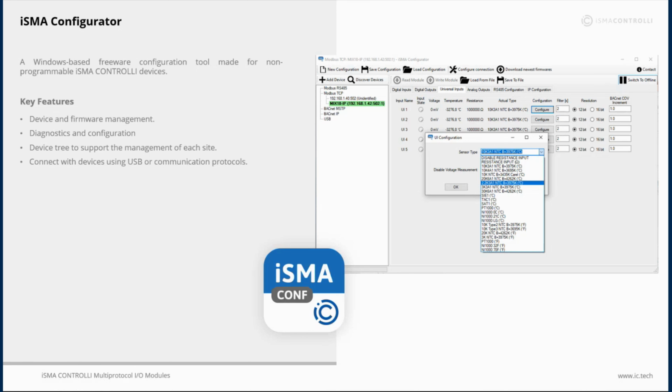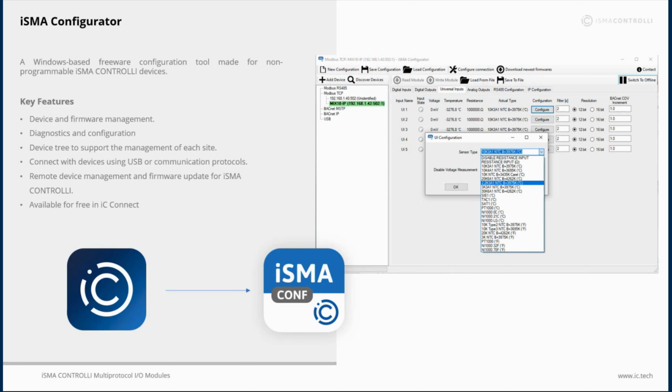You can connect to these devices, as I mentioned, to all devices using the mini USB cable, but you also have all those communication protocols implemented, and you can even do the discovery process over Modbus and BACnet. And what is important, even for devices connected over RS-485, you can remotely manage. We have a special module for Niagara for Modbus, and our products support products including MAC36 and JACE, which support BACnet routing. So you have a remote access not only to the IP devices, but also to the RS-485 devices connected to those controllers. So remote management is available within our products as well.